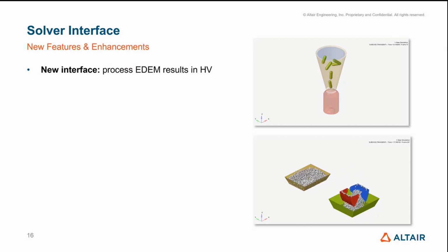So that would be the EDEM native outputs in HDF5 format. You simply have to load the file as model and result, and once you load, you can do all the basic post-processing in HyperView, like playing the animation, contouring certain results data, and so on.